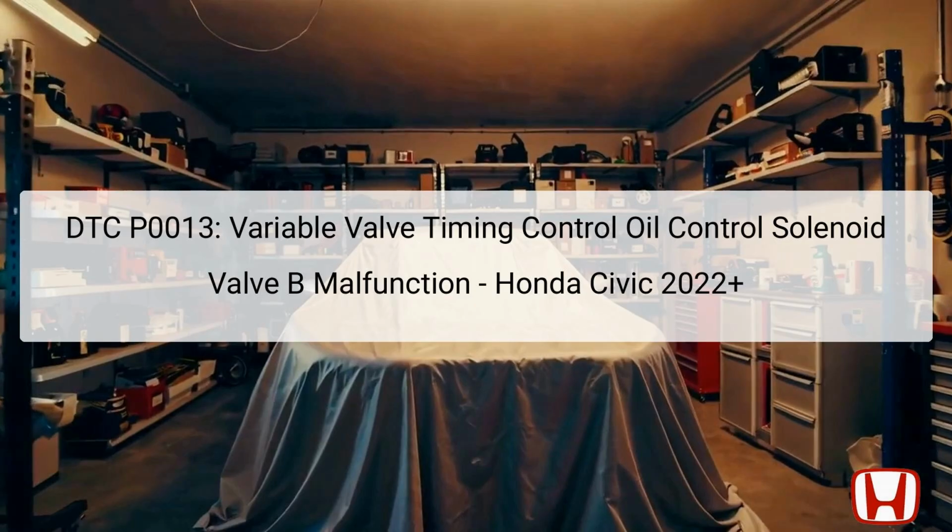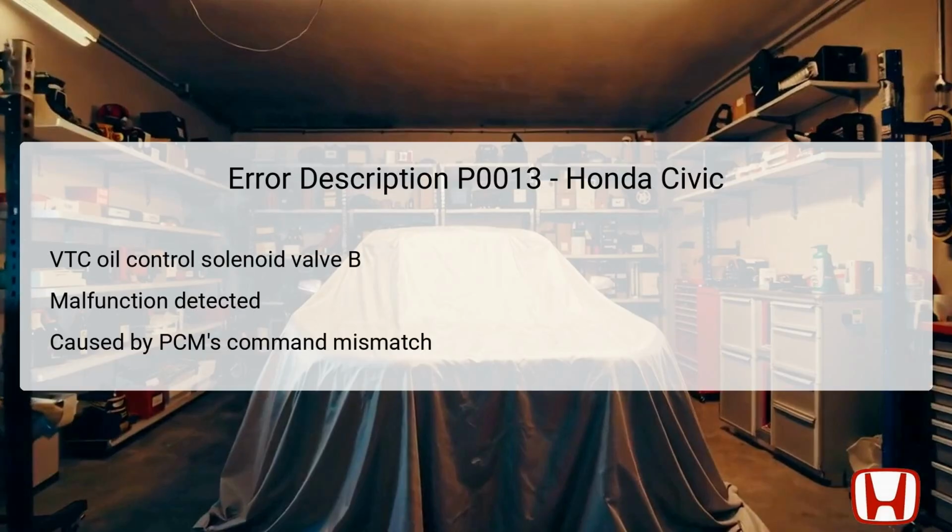The location of the VTC oil control solenoid valve B is specifically indicated within the engine assembly, often found near the cylinder head, where the oil passages are located for optimal performance. The DTC P0013 indicates a malfunction associated with the variable valve timing VTC oil control solenoid valve B. This solenoid controls the flow of engine oil to the VTC system, influencing the timing of valve operations, crucial for optimal engine performance and efficiency.